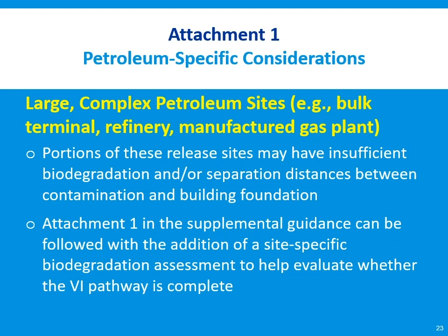However, for large or complex petroleum sites such as bulk fuel terminals, refineries, or manufactured gas plants, this supplemental guidance can be helpful. At these large sites, there may be portions of the site with insufficient biodegradation because of low oxygen, or there may not be adequate separation distance between the contamination and building foundations. In these cases, Attachment 1 can be followed, adding a site-specific biodegradation assessment to help evaluate whether the vapor intrusion pathway is complete. Thank you, and now I'll turn the presentation back over to Dan.